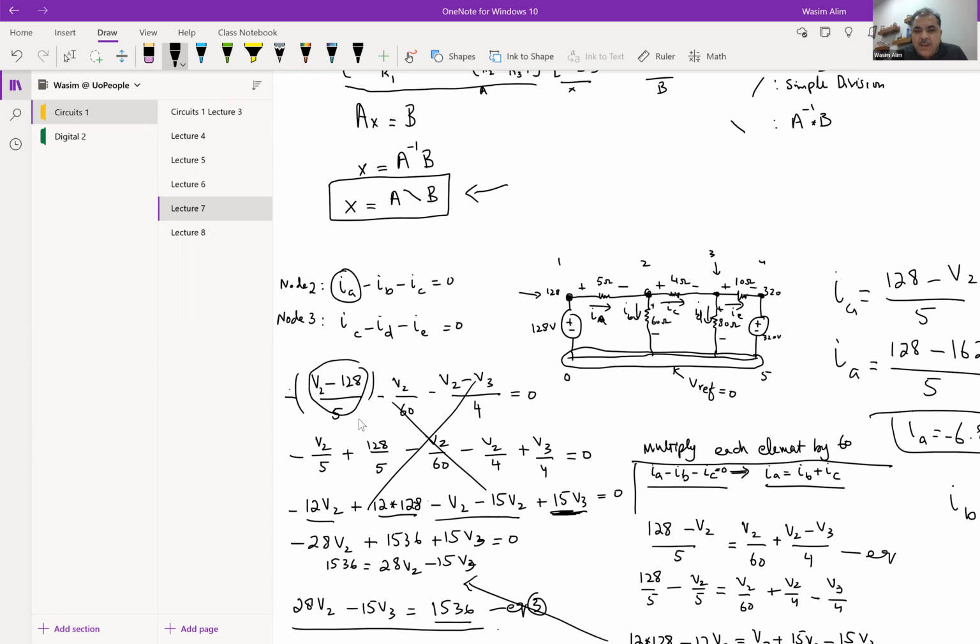Okay, so over here, we have determined that we have 5 nodes here, right? All of them qualify as combining at least two components: two resistors, or a resistor and a voltage source, or a voltage source and a voltage source. Now, if I look at node number 1, I can see what the voltage there is. For node number 5, I've already assigned a 0 voltage to that, so by definition it cannot be an independent node because we know the voltage is 0 there.